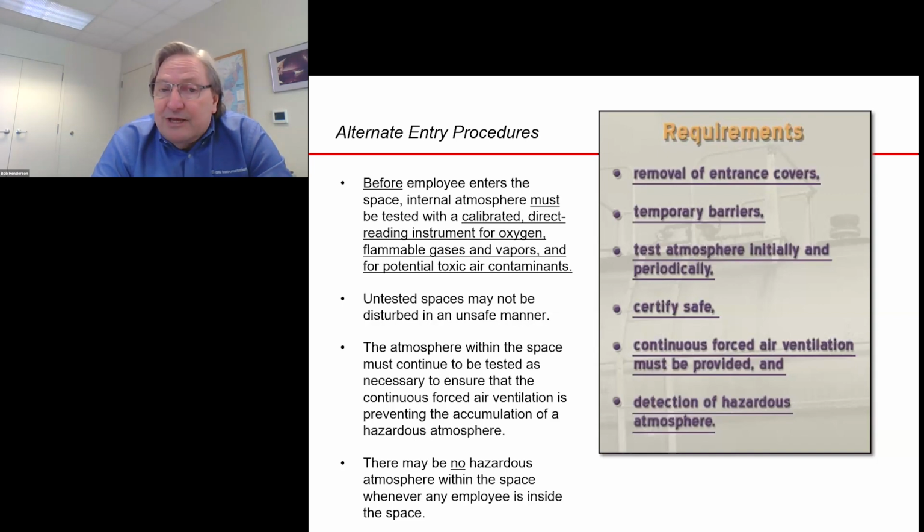Untested confined spaces may not be disturbed in an unsafe manner. The moment of maximum danger from an explosion standpoint is often before you're physically inside the confined space. If it's a manhole cover, methane, one of the most common combustible gases, which is a little bit lighter than air, can easily accumulate immediately beneath the lid. So if you strike the lid with a hammer, cause a spark, you can actually ignite the methane gas and you can have an explosion.